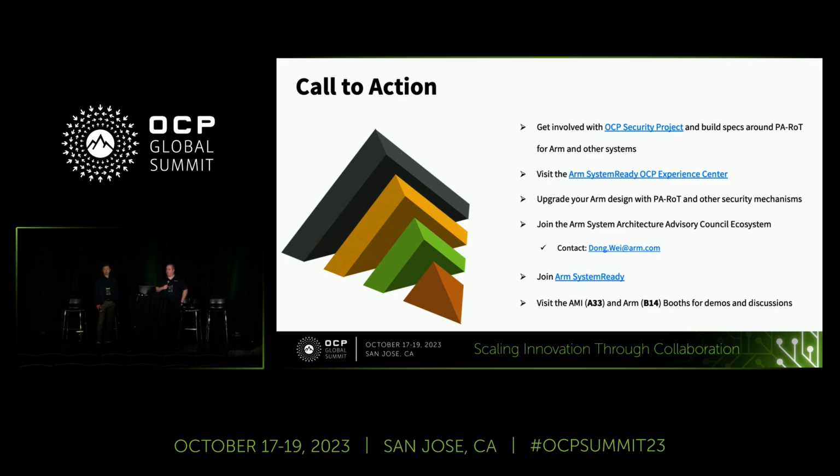Hi, similar in the vein to the other two questions, do you have recommendations on how to quarantine a device until it has passed authentication or attestation, like holding it in reset or bus master enable, et cetera? I would say probably the worst method, the one that we used in the demo, is to hold the system in reset, because then you've just created a brick. But it is an obvious thing when that would occur. Bus mastering, shutting down the root port, these sorts of things, outside of if you can recover the device. If you can recover the device, that's by far the best means to do it.